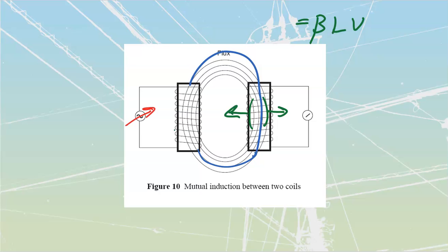Now what we're showing over here, holding one coil close to another coil, isn't going to be our most effective way of gaining mutual induction, because we're going to deal with what we refer to as fringing. Fringing is where some of my magnetic lines of flux are going to bow out and push around. We're also going to have some complete lines of flux that, because this thing has a certain number of lines of flux, it's too much work, and they're going to go around like this.